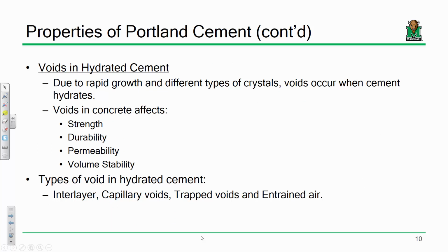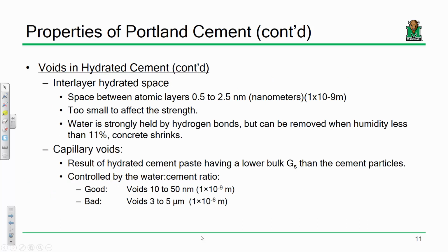We did talk about voids within cement, right? I think that's kind of where we stopped. The idea that when you hydrate cement, there is a chemical reaction, and there's going to be attraction between cement particles, aggregate particles, and water. Because of that, you do generate some air voids within a cementitious mixture. Some of them are desirable, some of them are not.